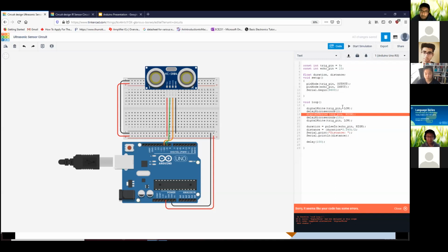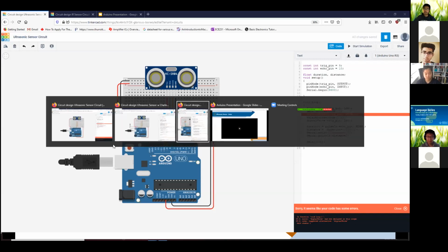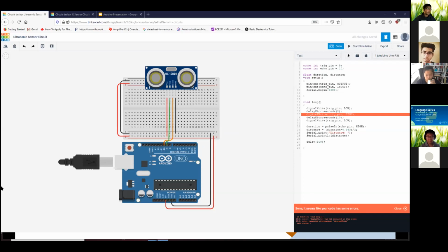Fahim, I think there's a question in the chat if you want to. Oh, sorry. Yeah, so great question. So the 9600 is the baud rate. Baud rate is like a data transfer rate, and the typical standard for it is 9600. Typically, as Martin has stated, the most common ones are 9600 and 115,200. Are there any more questions?